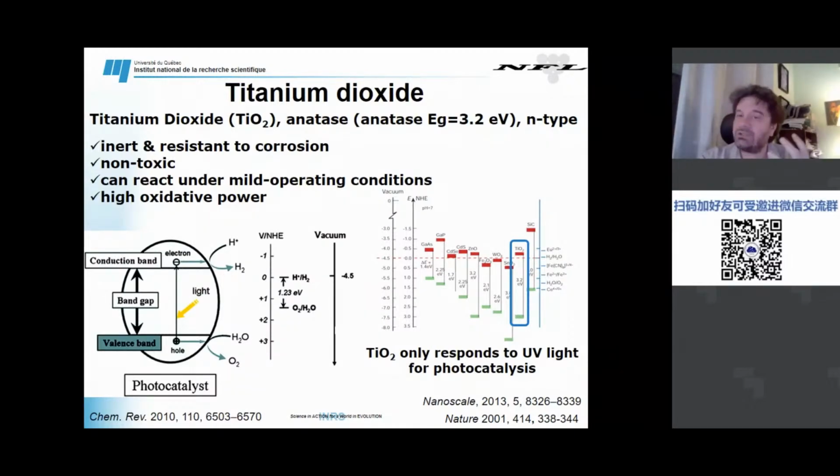The photon can create an excited state in the band gap. This excited state is called exciton, which has a short lifetime, and then it splits into two charges, an electron-hole pair, and then the charges are driven towards electrodes, so that you've succeeded in transforming energy in the form of a photon into charges, into electricity.